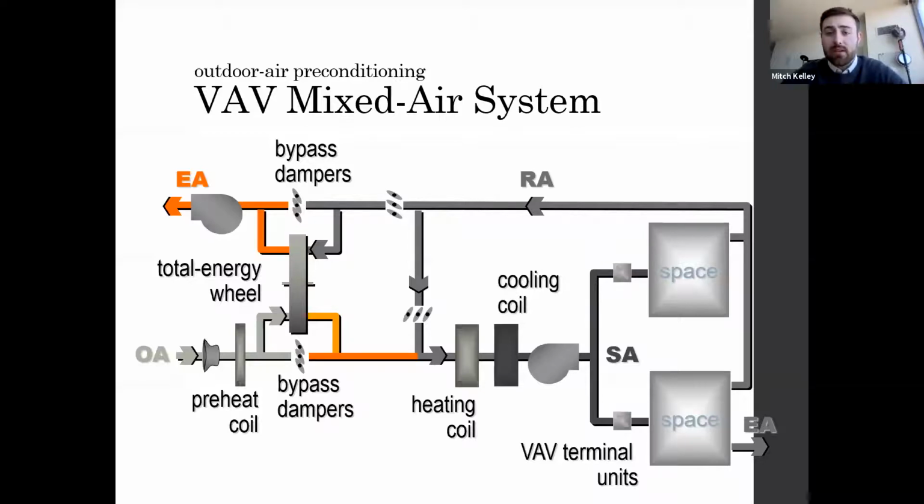When using a mixed air system, there are many climates where the use of an airside economizer can be beneficial for many hours of the year. When the system is operating in the economizer mode, the energy recovery provides no outdoor air preconditioning benefit. In fact, if the energy recovery device is not turned off, it actually adds heat to the supply airstream, increasing the cooling load. Proper economizer operation and integration of the energy recovery device into the system control mode allows you to maximize energy savings and minimize the payback period for the energy recovery device in question.